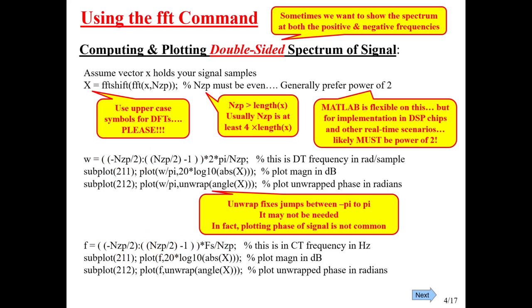So when I multiply that, the sequence of integers times fs, I get something that will go from minus fs over 2 up to just shy of plus fs over 2. So the same things that correspond to the minus pi and just shy of pi that I had up there. I like that little rhyme. It helps me remember. Minus pi to just shy of pi.